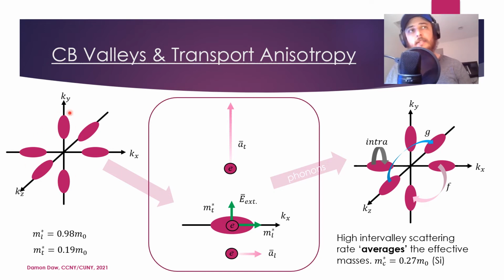And what that means is, for example, say you photoionize again a bunch of carriers, and you have a bunch of electrons that get a bunch of energy. They start emitting phonons, and they settle to the bottom of the conduction band. Each one of these valleys will be populated with an equal number of electrons in different energy states corresponding to the different valleys. And what's unique about this is if you apply an external field to electrons in these valleys, they will accelerate with a mass that is different depending on the angle that the external electric field makes with the crystal.